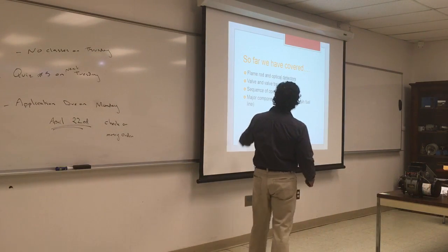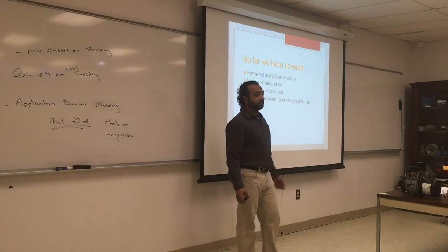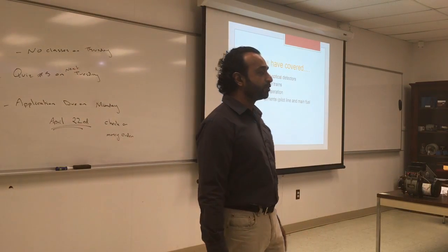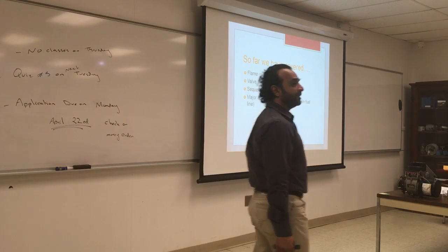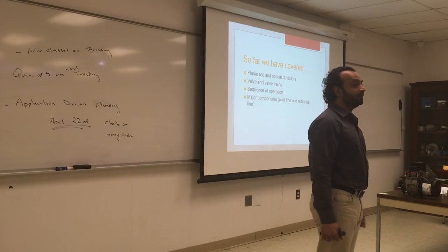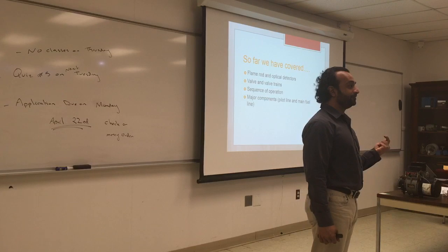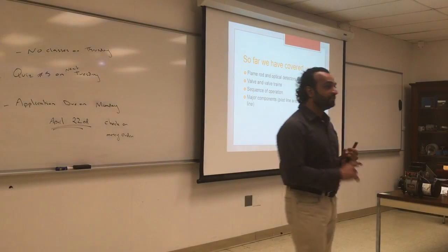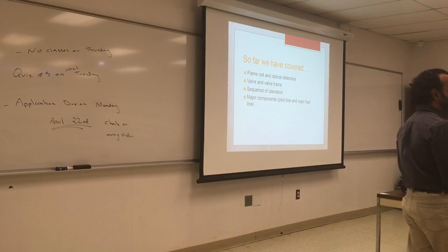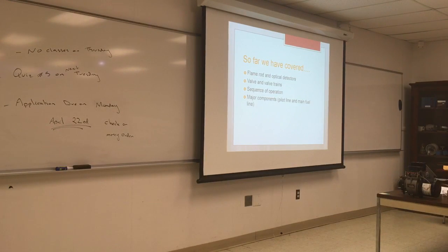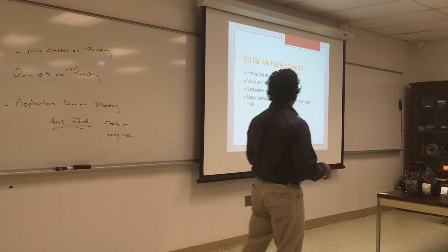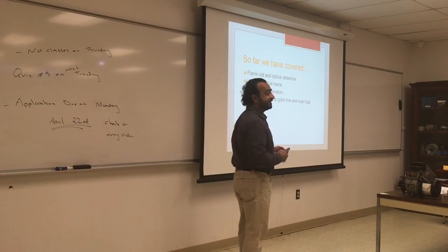So we covered flame rods and optical detectors. I would say a flame rod is a steel rod covered with ceramic or porcelain, and it reacts with what? What in the flame? Ions. So we said flame produces light, heat, sometimes some particles, and also some ions. Ionization is when the matter transforms into plasma. So it reacts with the ions to do identification.